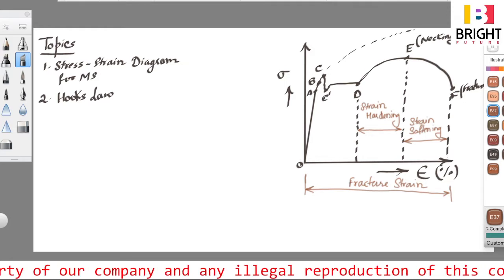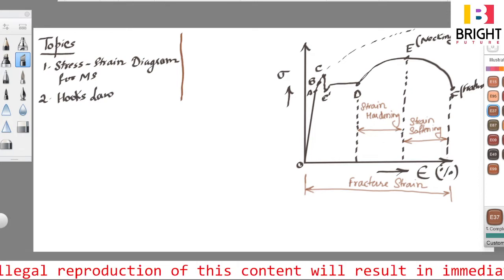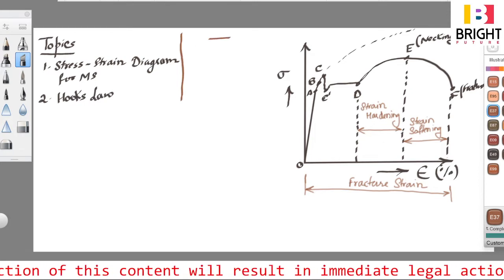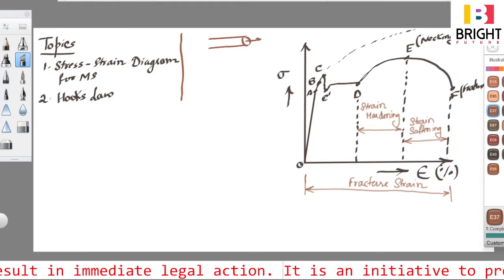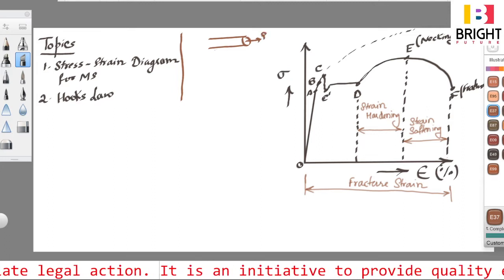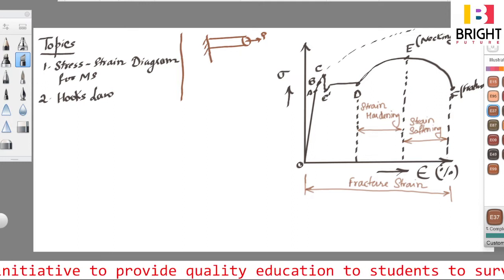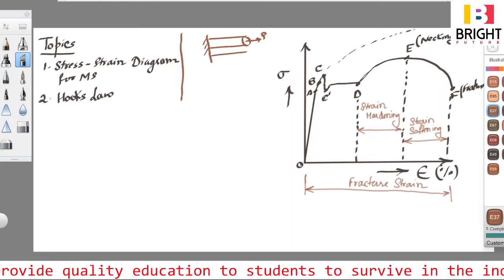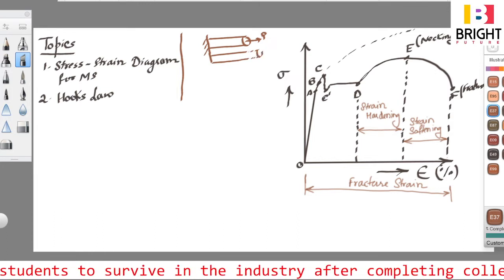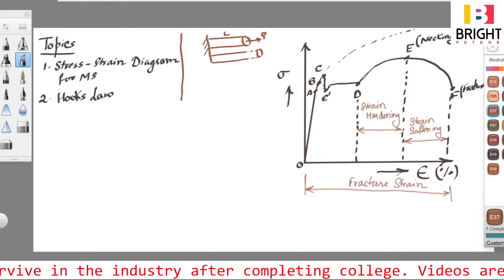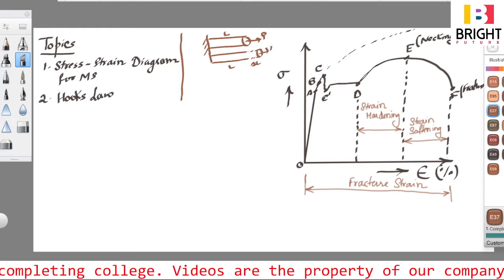One more concept is there, which we call strain. Let me discuss this. In the last lecture it was not discussed. For example, there is a rod like this, and we apply some normal load P, and under the application of this load, with this side fixed, its dimension increased to some extent. The increased length is represented like the dotted one. So the original length was L, and the new length is L plus del L, which is increased under this load.